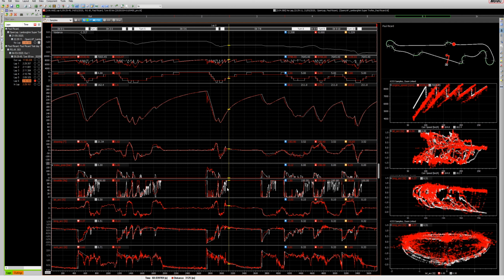In terms of throttle application, we can see that the white line has much more noise in it than the red line. Keep in mind that this car in reality has traction control. So basically what OpenLAP does is activate the traction control by itself. Also, the TPS map is not linear with power, but in OpenLAP it is. So you might see differences in the shape in general.